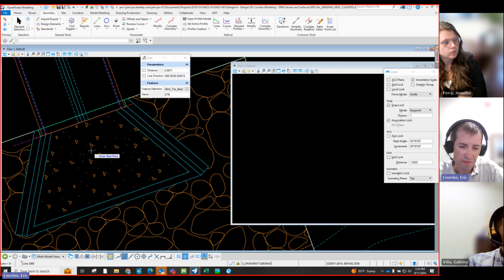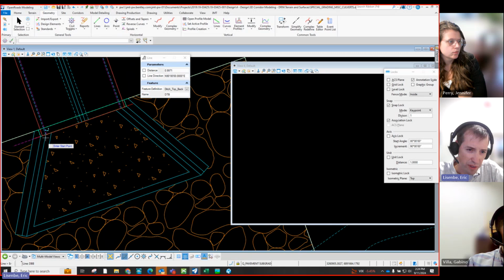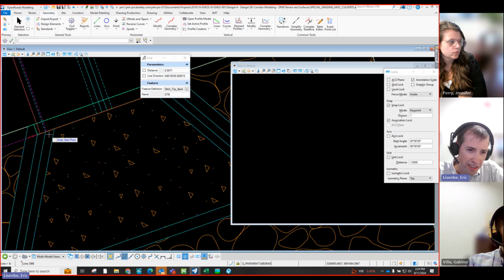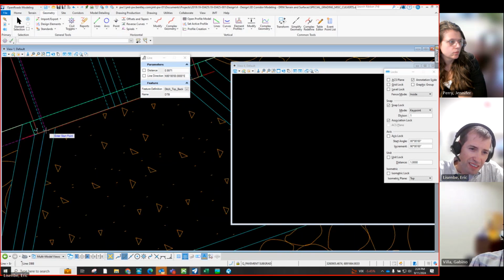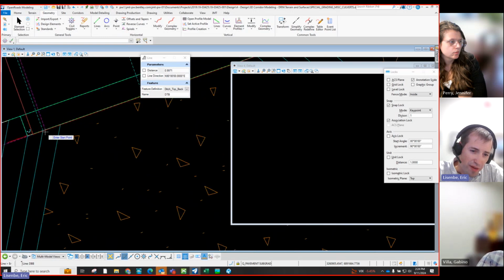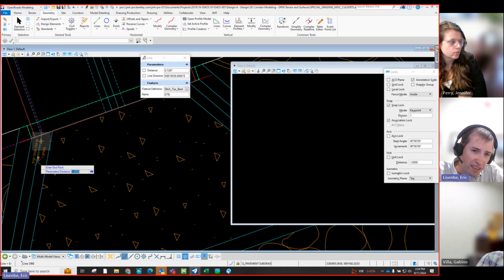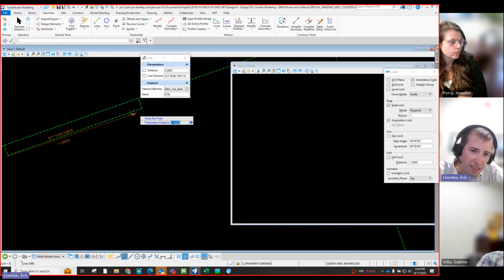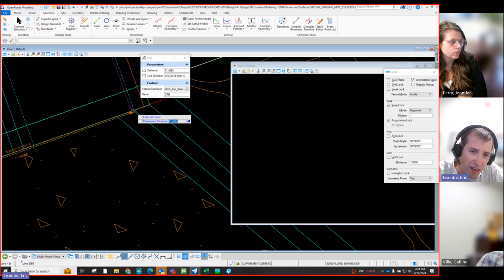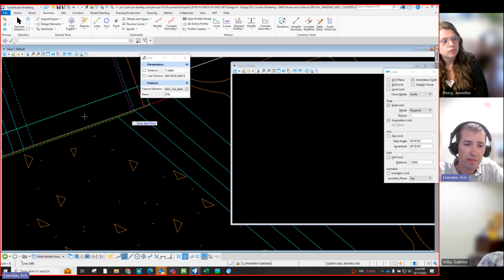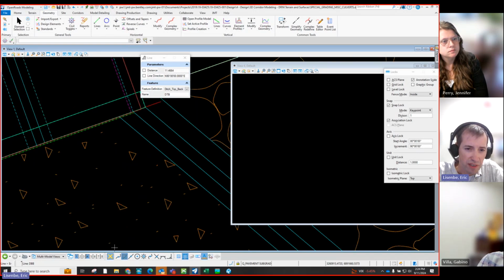And then we put some other line work that I'll use to define it. Now, these are touching each other. For making a surface, I'll probably make it not quite touching itself so it doesn't blow up. And then give it a line down here. This is going to be a steep drop off, and I'm going to give it the flow line elevation of our culvert. Turn my snaps back on.